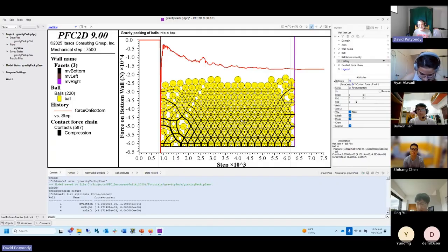And for granular material, it's very sensitive to size. And you can't directly always translate a small scale test into that. So the result of all this is they use PFC to try to answer some of those questions about the granular flow. And so I was working with those guys some years back, and they told me this story. They told me that if you actually study granular flow, the first thing you learn is that a large amount of load gets carried in the walls of these bins.